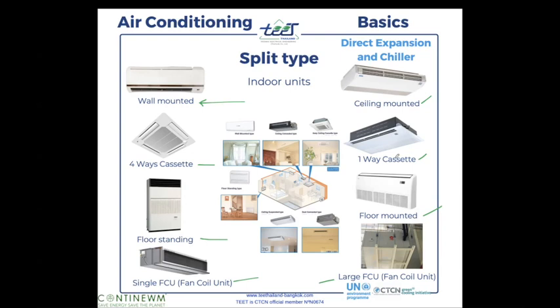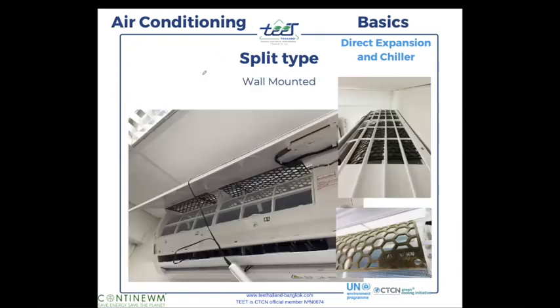So when you see this, it doesn't mean that it's a direct expansion with a compressor, because you can have a heat pump with the water from the chiller. In general, this model is used with a compressor, but it's just in general. You have cases where you can have water from the chiller.